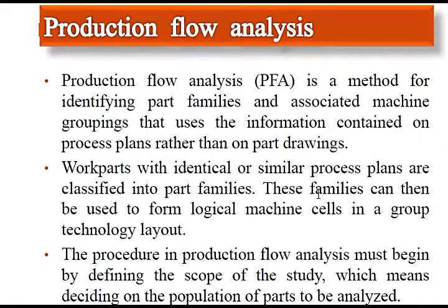The second one is production flow analysis, or PFA. PFA is a method for identifying part families and associating machine groupings with information contained on the process plan rather than the part drawing. Work parts with identical or similar process plans are classified into the part family. This family can then be used to form logical machine cells in group technology.